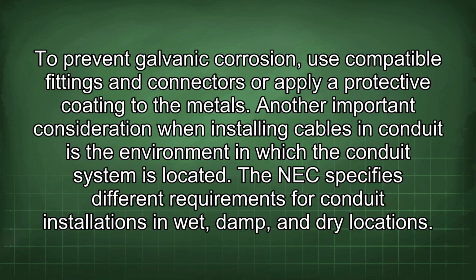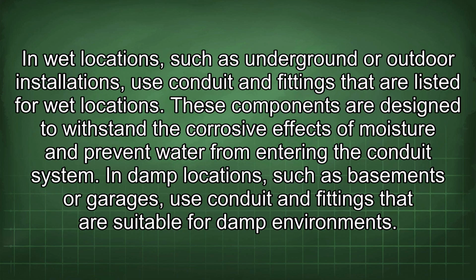Another important consideration when installing cables in conduit is the environment in which the conduit system is located. The NEC specifies different requirements for conduit installations in wet, damp, and dry locations. In wet locations, such as underground or outdoor installations, use conduit and fittings that are listed for wet locations. These components are designed to withstand the corrosive effects of moisture and prevent water from entering the conduit system.